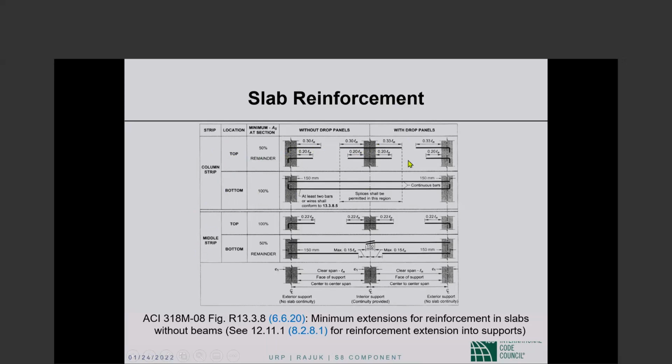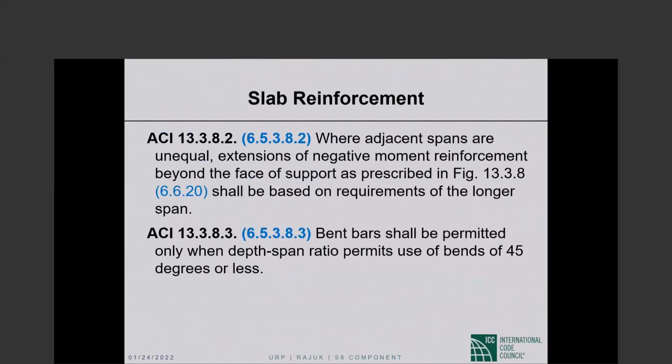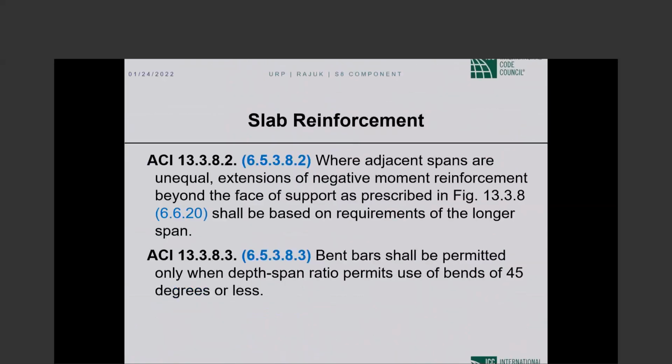Okay, so this picture is an absolute necessity to understand and to comply with. So please take a look. I will not be able to improve anything by dwelling on every number here, but I do want you to understand that this very important picture is part of the code and you are supposed to follow it. So reinforcement in slab shall have minimum extensions as prescribed in that figure.